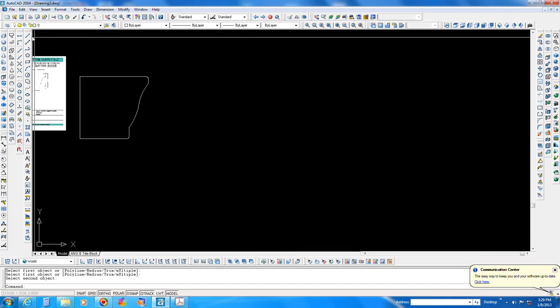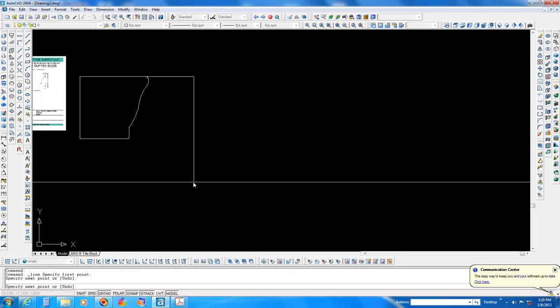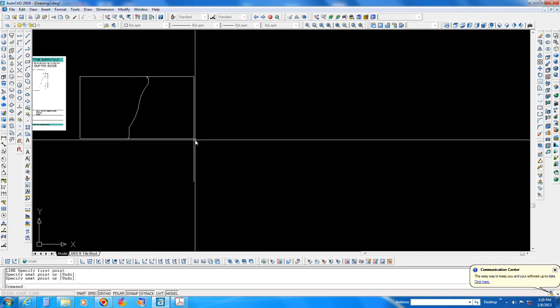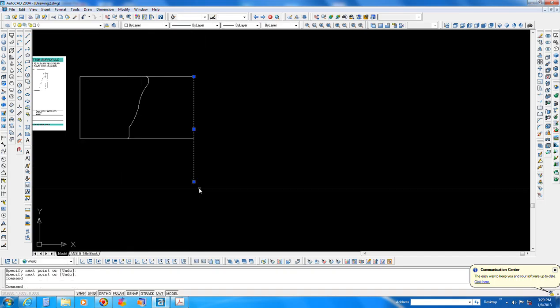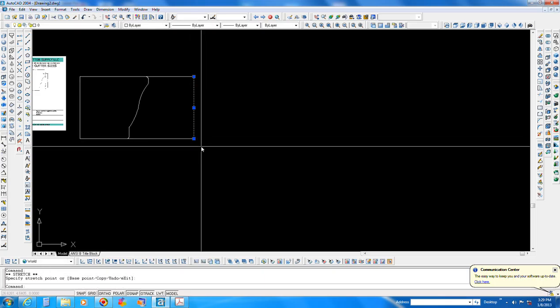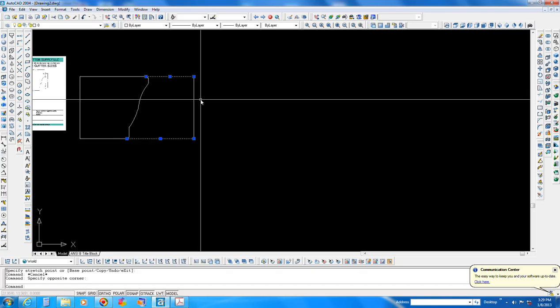Okay, so now that we've got our size here, what we're going to do is geometrically construct this to there. With AutoCAD, you can actually grab a line and its endpoint, and as long as it's modifiable, you can actually trim it just like that. We'll erase these lines.